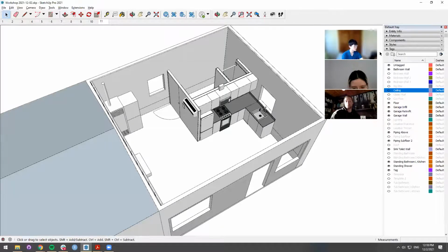Yeah, so we didn't encounter a requirement at the Title 24 level. I think it was more the building code requirement for a certain amount of natural ventilation that's possible through your existing attic and your ability to have operable windows, and I guess a certain applied infiltration rate to your existing space. Because we're going with a non-air-based system, especially if there's something that's like $200 that works well in a wall, then that would be a no-brainer to just include by default.